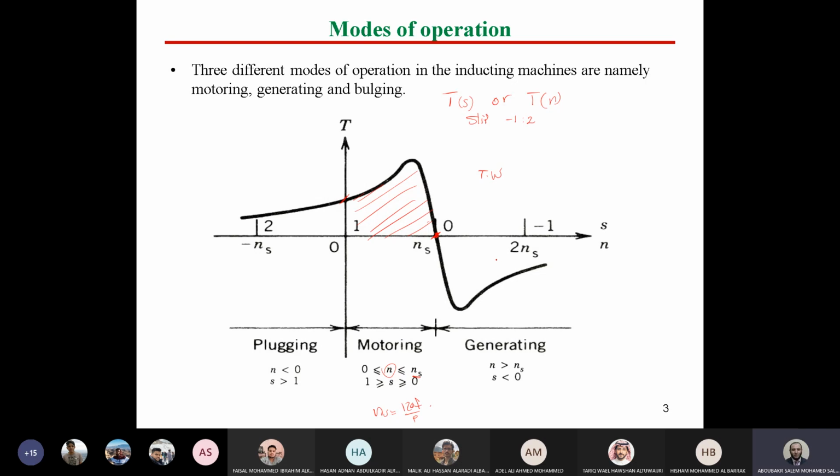So the power flow will be negative compared to the motoring mode. And this is expected because for a generator compared to a motor, the power flow will be inversed. How can it be inversed here? By inversing the torque sign. So this is now called generation of power. If the machine is working in that mode, the machine will work as a generator.